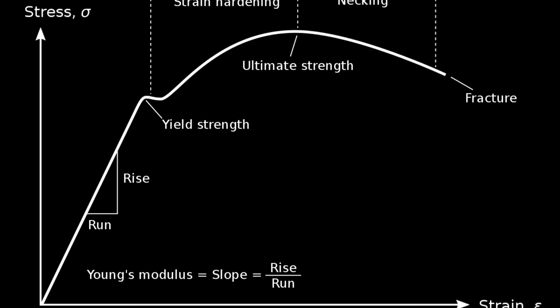If you've ever seen a video of a metal rod having a tension test, a tensile strength test, you can see what plastic deformation is. And necking happens around there. That's where the metal starts to thin out in the middle, and then it finally snaps. And that's what plastic is. If you let go of the rod right when it's starting to pinch and thin out, it's not going to snap back to normal. You've plastically deformed it at that point. It's ruined. You can't use that anymore. So if that's happening to a part on the bot, that is very bad, and you need to avoid that. That's the reason you would use a simulation like this.